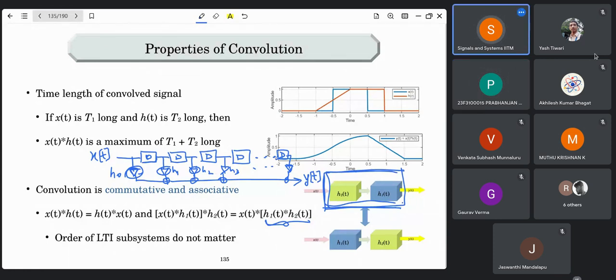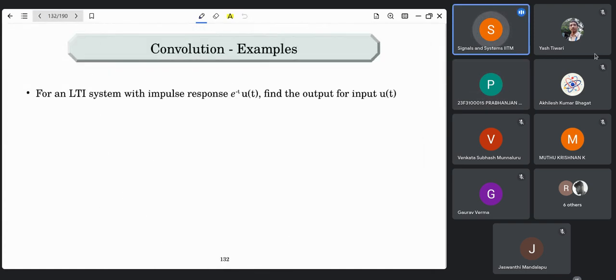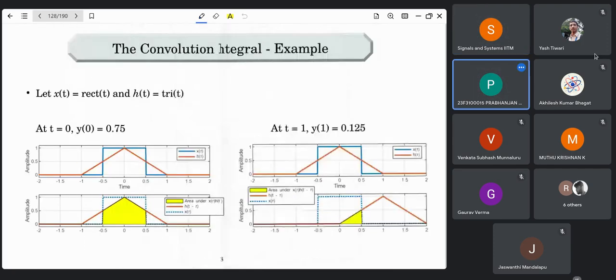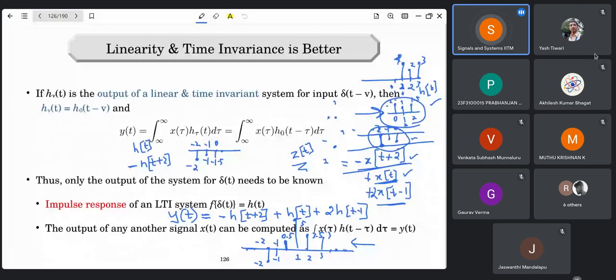Any other question? Professor, one question. For the convolution, why are we reversing one signal? Is there any other reason than, I mean, imposing it from the origin to the end? So I was explaining with this discrete time example, right? You can see what happens here. The input's first sample is -2, right? That is what needs to be added first.